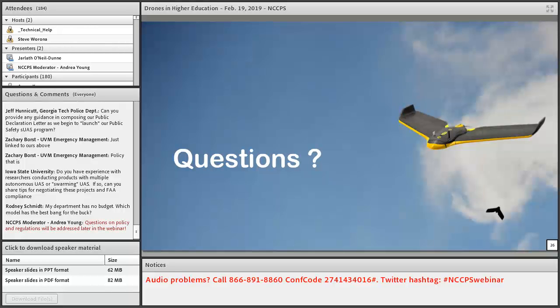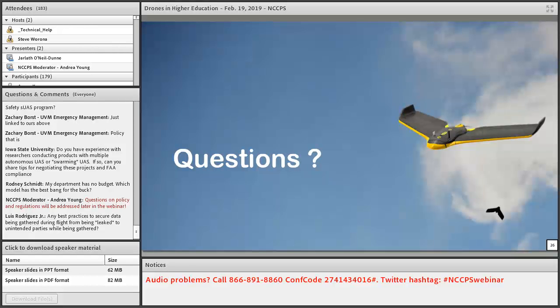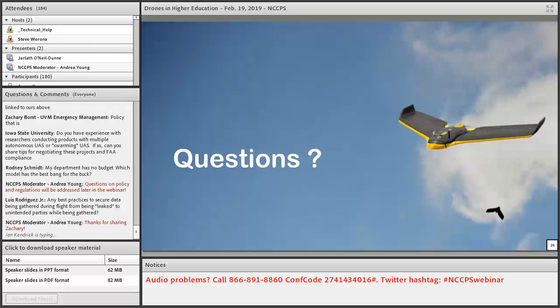But for now, someone wonders, what is the average weight for a fixed-wing UAV platform and payload that you prefer to use? Sure. So one of the reasons why we like the fixed-wing platforms is they're inherently safer. Compared to the multi-rotor platforms, where if they lose power, they're going to fall straight from the sky, with these styrofoam fixed-wing platforms, most are in the 2 to 5 pound range. And when they lose power, they will glide to the ground, and they'll probably hit you with about the kinetic energy of a soccer ball. So when you think about safety and risks, not all drones are created equal.